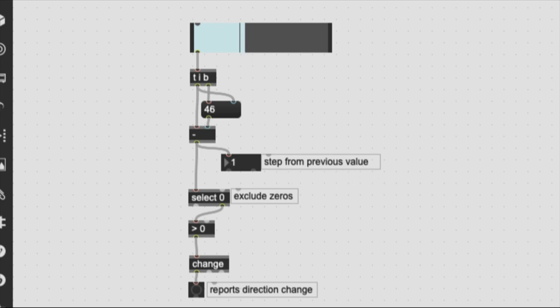So you see, if I move in a positive direction, typically I get ones, but sometimes I get a 0, which means that this slider object has reported the same value twice. Can happen. It depends on the implementation. I believe in this case it's because the mouse resolution is slightly higher than the dial resolution. So you can move a mouse, it reports the movement, but it actually hasn't gone a full step up. You could have implementations where there is no repetition of values.